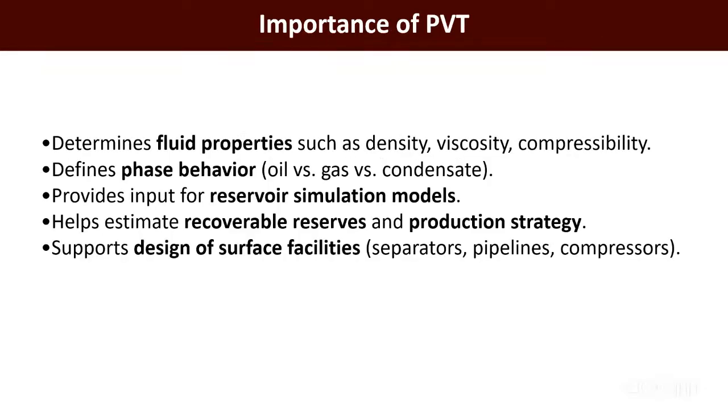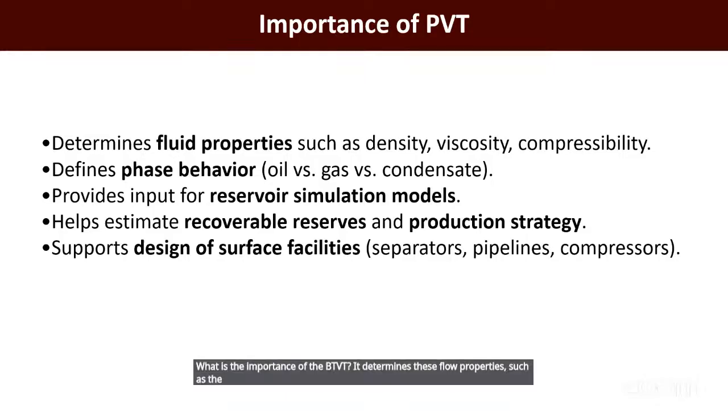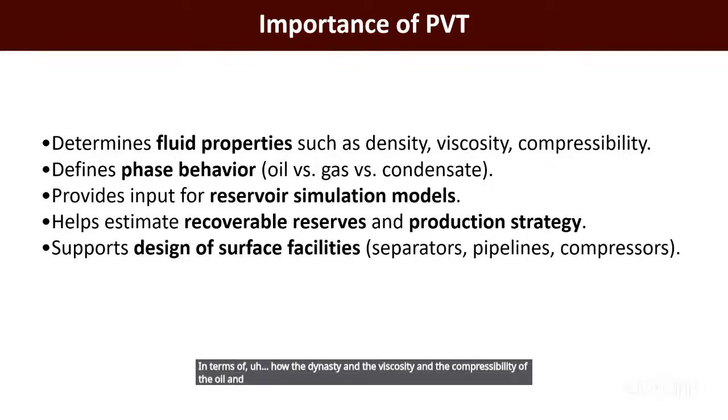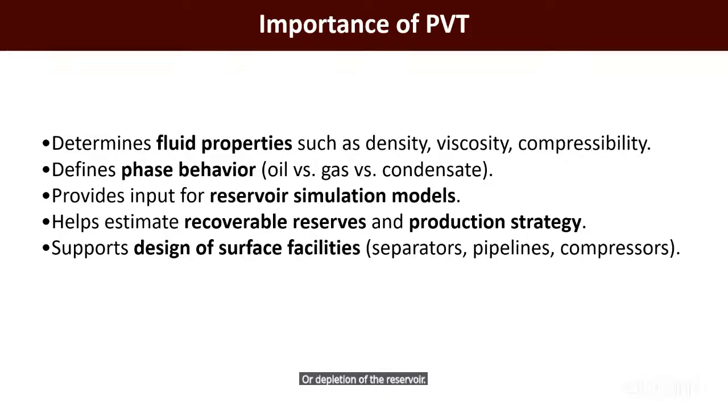What is the importance of the PVT? It determines fluid properties such as the density, the viscosity, and the compressibility under different conditions, in terms of how the density, viscosity, and compressibility of the oil and gas will change when we have a pressure drop or depletion of the reservoir. Also, it defines the phase behavior of oil, gas, and condensate.